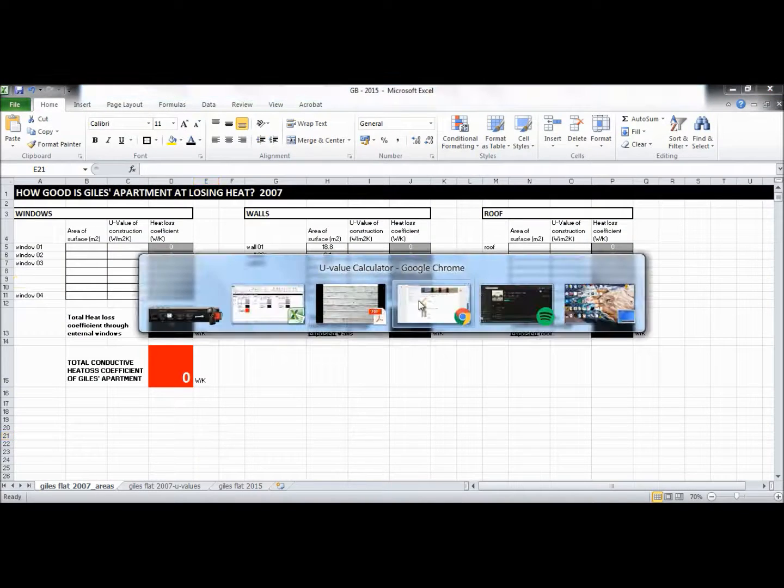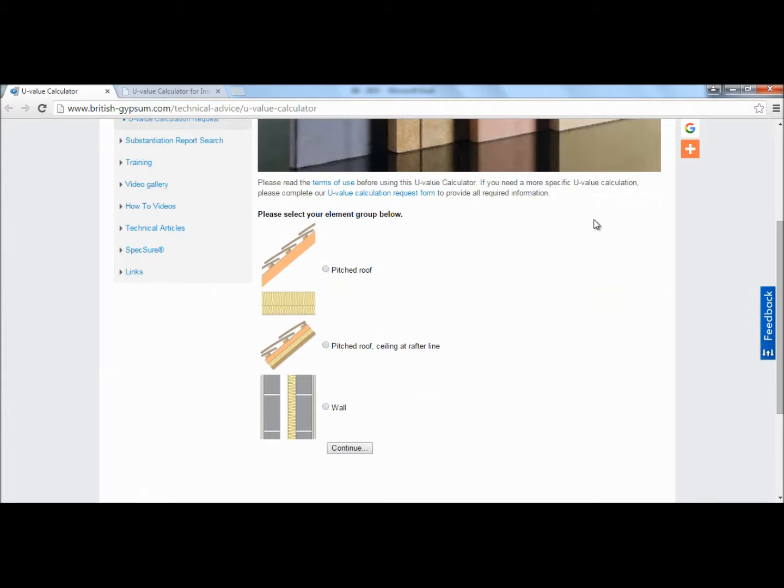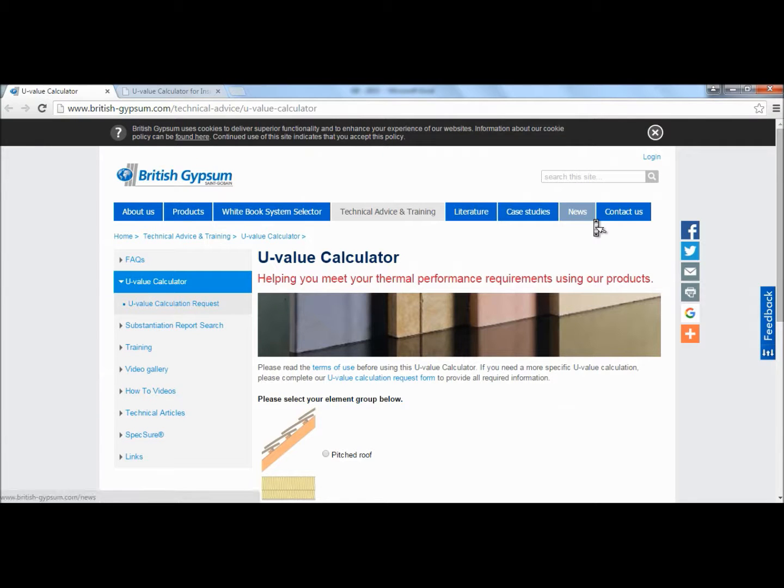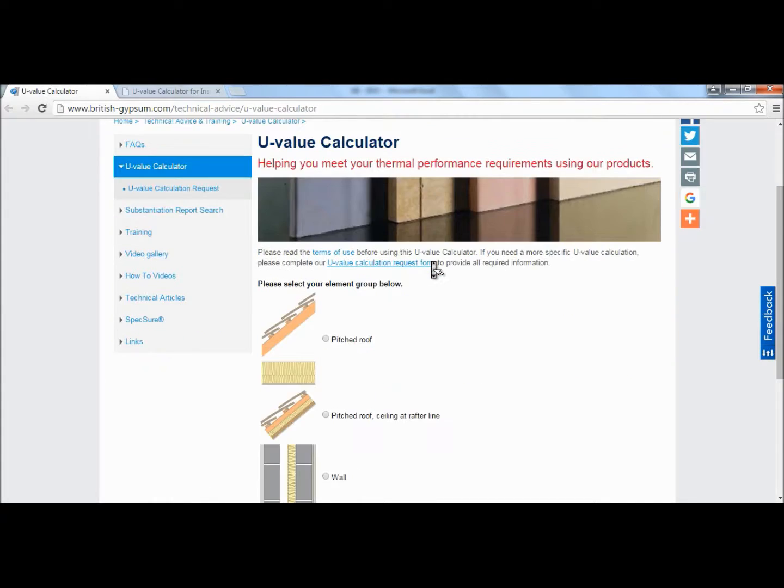That is important for me to know because the depth of the material and also the material itself, which has a certain ability to conduct heat, those two things are going to give me the U value. So I want you to have a look, and like I've done, photograph that wall so that you can understand what it is. Now, the website that I've given you is this website. There are many such websites, but I've just picked this one, and this allows you to understand the U value.